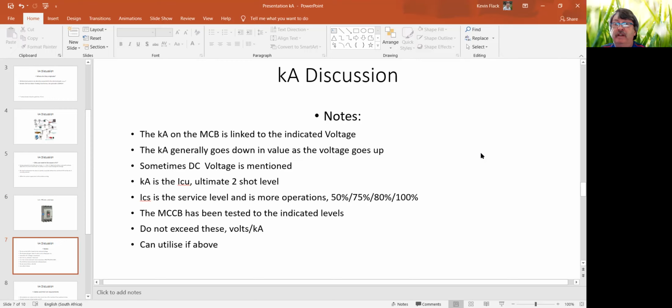You need to understand that DC being a positive and a negative only, on the three-phase breaker, you need to be able to wire it in a certain way. As you can see, the DC kA is actually quite low relatively. So by reasoning, we can see that the DC is quite damaging to a circuit breaker compared. And of course, some circuit breakers may not have DC qualification whatsoever. And on others, you might have only DC breakers where they've not been qualified for AC.